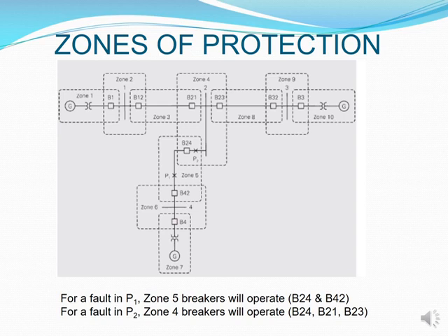There must be a circuit breaker involved in it. So you make sure that each of your equipment has a circuit breaker that is covering it up. And usually your lines and your bus bars, on either side there should be circuit breakers that look after them. And that's how you would be able to circle or identify what your zones are.